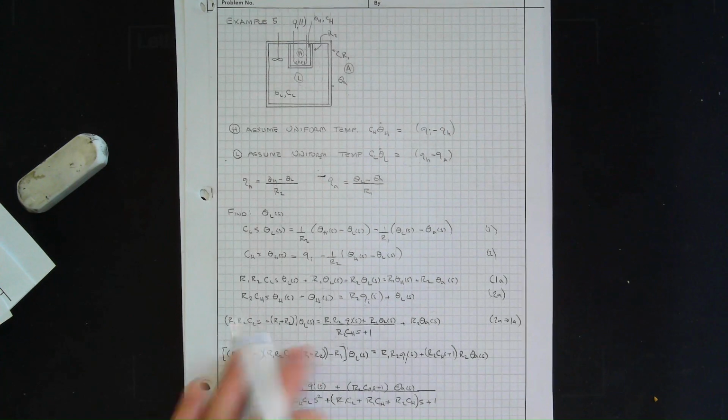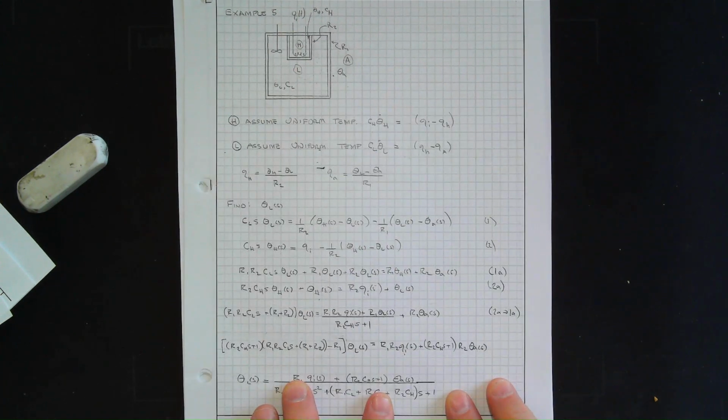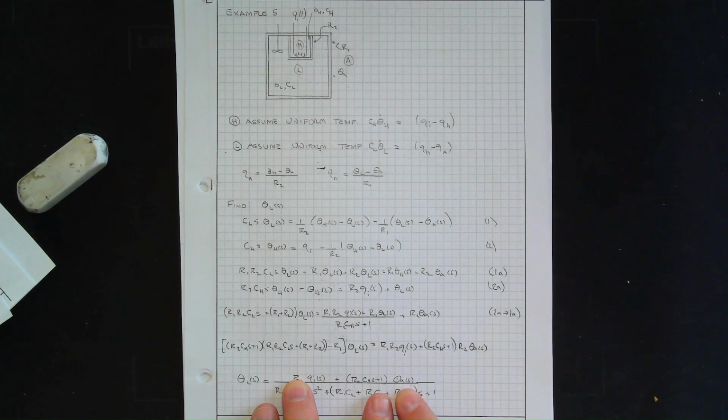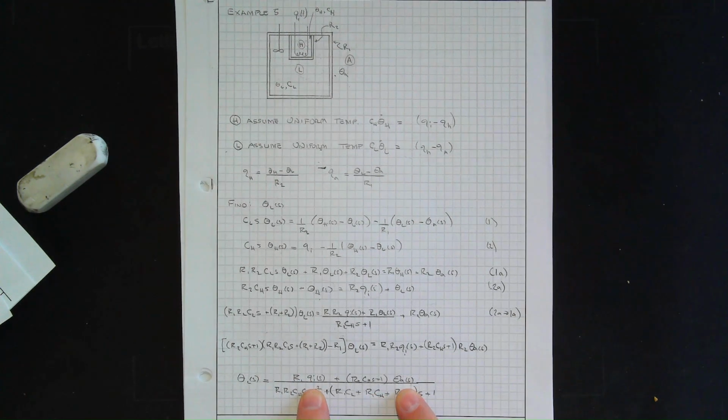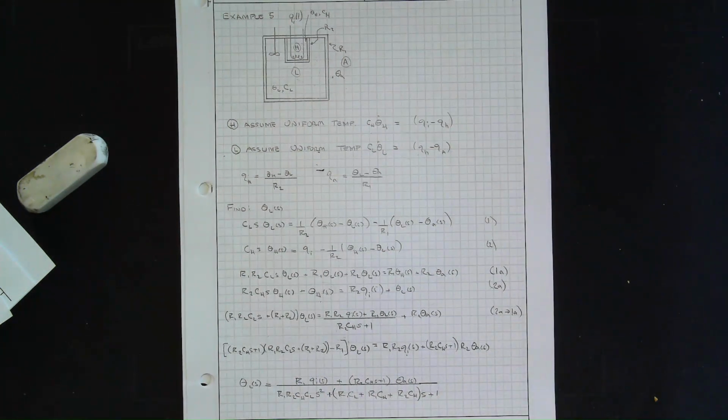And so now we just divide everything through, and we can make this into two transfer functions, one relative to theta A as an input, and one relative to the supplied heat as an input. And that's the problem. All of which can be put into Simulink if you want to. And with that, we're done with our heat systems.